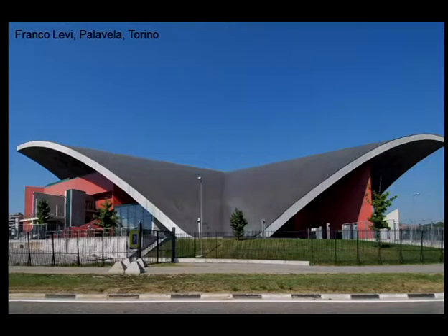But also a little bit of cantilever is possible in some cases, and this is a bad example of architecture because it was developed in the 60s just as a shell, and the idea of shells is always the large span. So the idea is that the space underneath is without intermediate supports. I don't want columns, I don't want extra elements. I just want to be free to place whatever I want. That's why it's generally used for stadiums or train stations. You generally find this type of topologies in these type of structures.